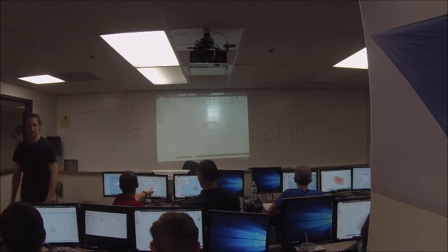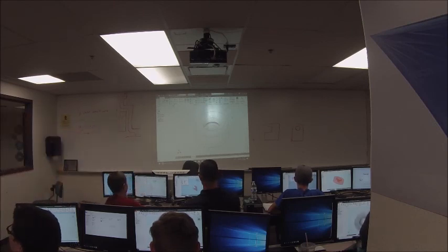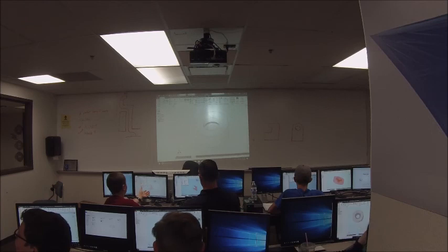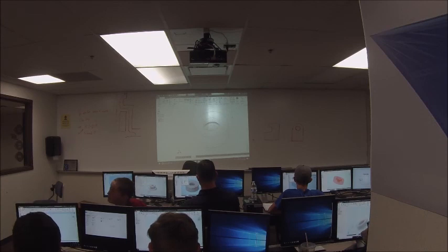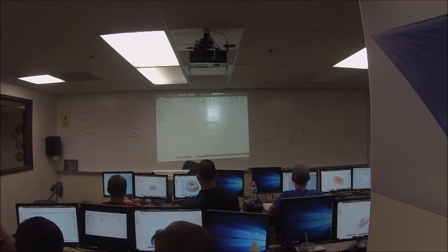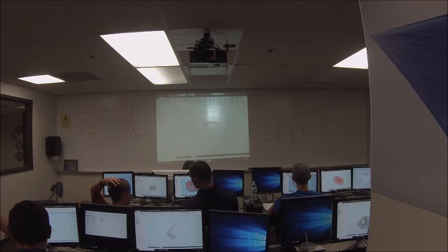Is there a normal to button? Oh, you want to view your sketch? That's what that is. Now you'll have to go over here to the planes to click which plane you want, because you don't have any surfaces.